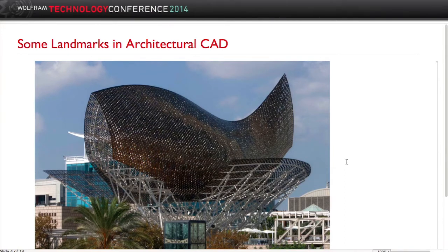And the reason is the mesh-based model approximates the curvilinear surface with planar facets. And you know, the smaller the facets, the better approximation you get. But that was still not sufficient to actually build the thing, to get all of the thousands of connections in here, you know, millimeter precise, so that everything fits together the way it should. So they turned to another industry that had experience actually designing curvilinear surfaces by computer, the aircraft industry, and Dassault Systems, a French company, and their product CATIA. So CATIA is a NURBS-based system.